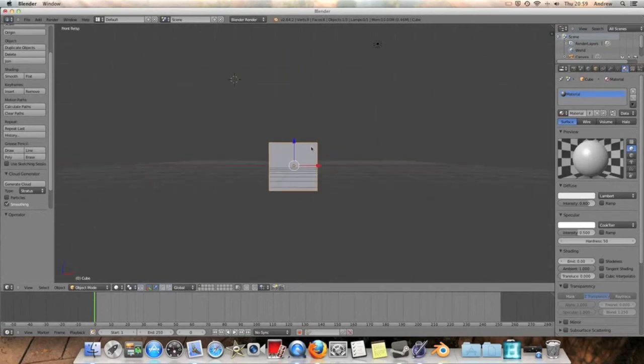But if I press 5 again it's pretty much a flat square, but we are actually still seeing it a little bit differently. So if I view it from this side here and I press 5, there's not a massive difference, but it is actually removing perspective from the scene, and that makes it a little bit easier when you're going to the side view, because you can accurately see your object directly, and it becomes more useful later on. It's just if I press 7 and things, it's a lot easier to see what you're doing. So that's the views. The final one is pressing 0.